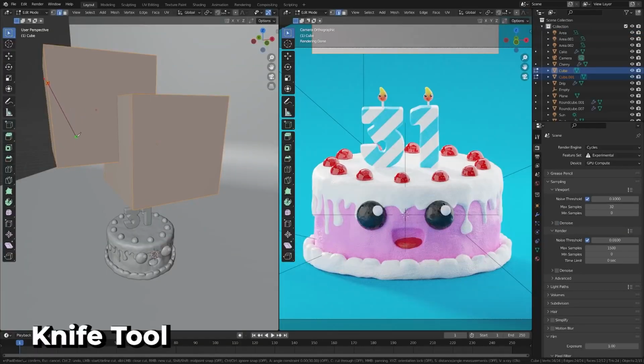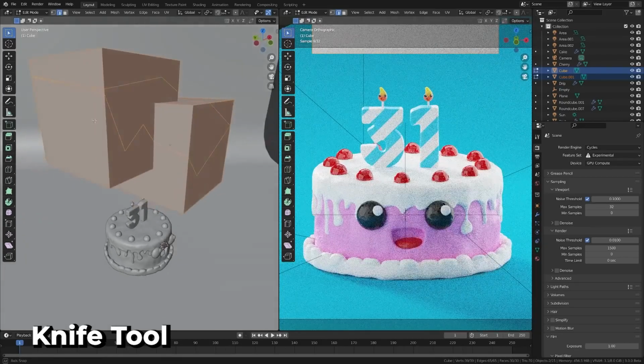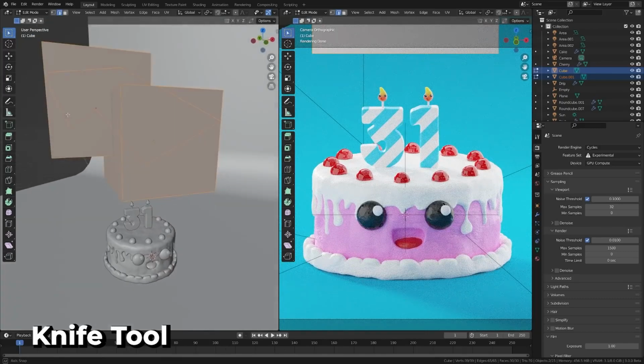The knife tool just got a whole lot better. The constrained angle mode has been improved and it's easier to snap into place. You can turn this on by default now too. Pressing S will toggle measurements for distance and angles, and you can now undo your previous cuts. There's an X-ray mode with depth checking, and now you can use it for multi-object edit mode.